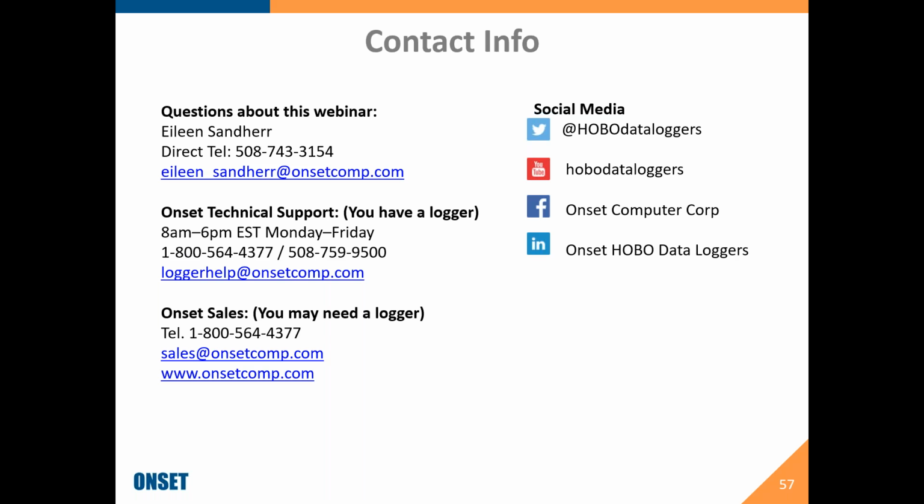So Eileen, if you want to talk a little bit about the input options with the UX120-06M, which is also available as a Bluetooth data logger, and that is the MX1105, and those are analog inputs. Did you want to talk a little bit about the different options you have for that specific logger? Sure, happy to. Great data logger. You can have one choice that has temperature, relative humidity, and light built in with one open channel, and you have a 4-channel.